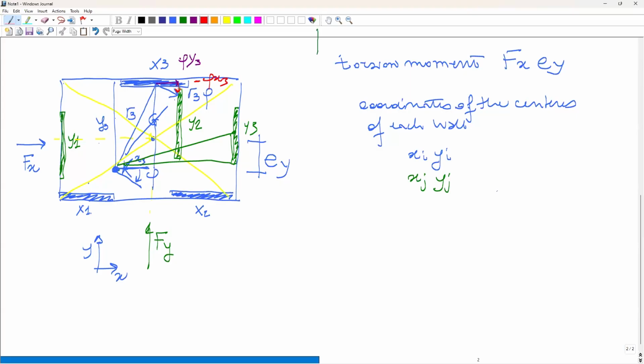This displacement will have two components, one in x and one in y direction. Here we bring back our main assumption, and we say for walls in the x direction, the stiffness contribution that they provide for a displacement in y is negligible, whereas we only consider the displacement parallel to that.